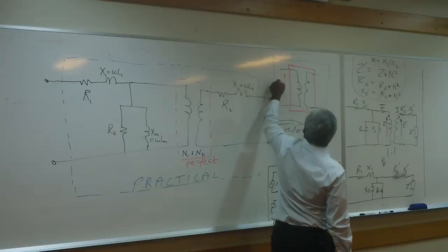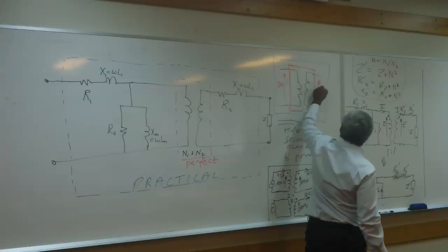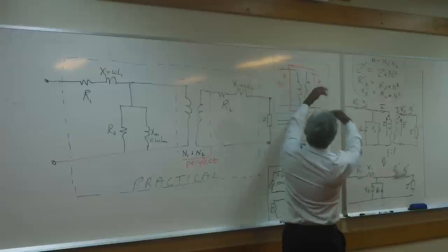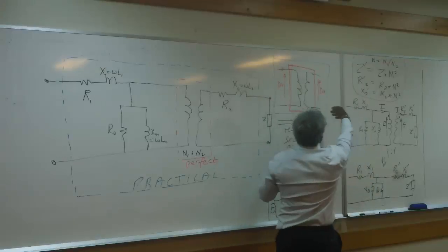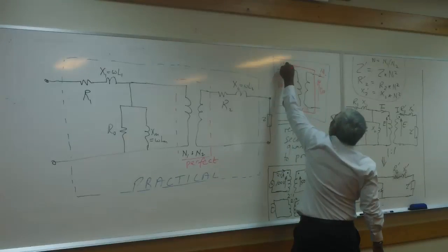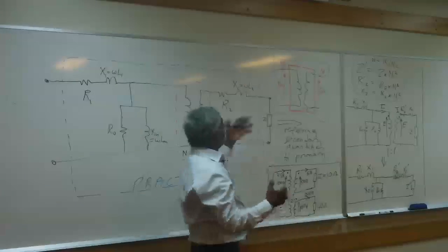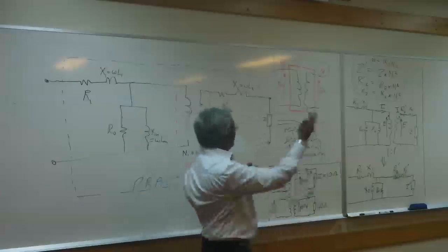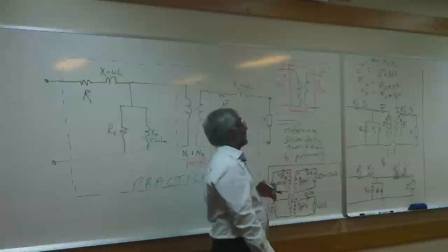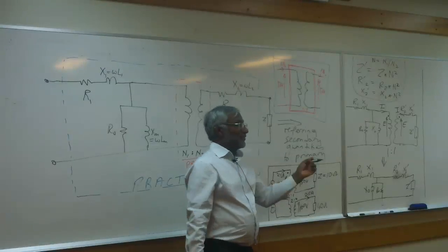Indeed, if you put 50 volts there, AC, you can see, I'll prove to you there's 50 volts there, and I say to you, look, we'll inject so that it's 1 amp, so we put 50 ohms on the other side, and that gives 1 amp, and you see 1 amp there, and you say, well, theory perfect, it's 1-to-1, 50 volts primary, 50 volts secondary, 1 amp, that fits every theory you've ever learned about the perfect transformer, and you say, okay, there's your $50.